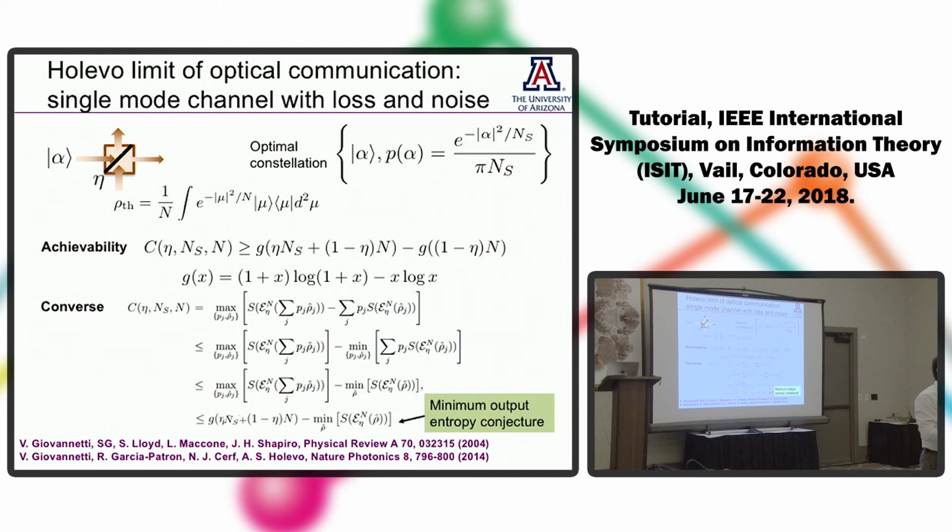So in the microwave domain, thermal noise per mode is so high that some of these quantum benefits of joint detection receivers are completely wiped away, meaning doing a heterodyne receiver, which induces an AWGN channel, is probably the best thing or close to the best thing to do. Which is why all of this wireless information theory that you see in ISIT starts from AWGN, and that's perfectly justified because they're working at such a long wavelength that some of these quantum effects are completely washed away.